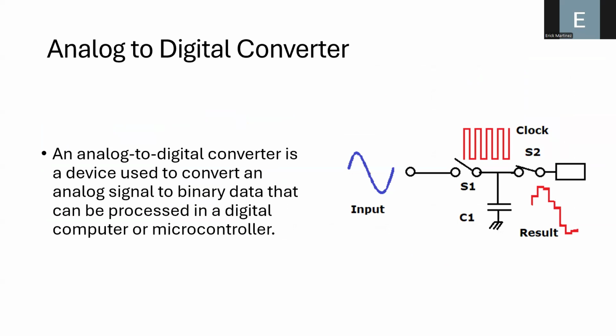We have amplified and we have filtered the signal. But now we need to perform another task. Now I want to collect the data with a data acquisition card. How can we do that? All of the data acquisition cards have an embedded electronic circuit called the analog to digital converter. Basically, the analog to digital converter takes the input signal and takes samples of it at a particular time interval. We call that time interval the sampling frequency.